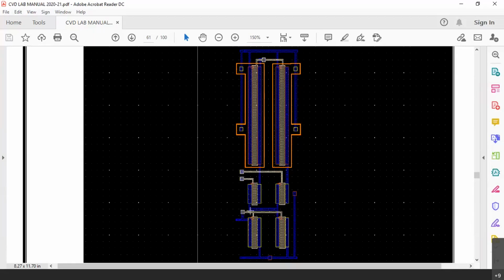And the source of left side NMOS and the right side NMOS, they are connected together. They are connected to the drain of the biasing transistor. This right side NMOS is the biasing transistor. And its source is connected to VSS. Lowermost one is VSS. Similarly, we have this current source at the left side, that is the NMOS. This is the IDC point here. And you can see the IDC is connected to the drain also, to the gate also, because gate and drain are shorted there. Now the shorting is done by means of one more via.